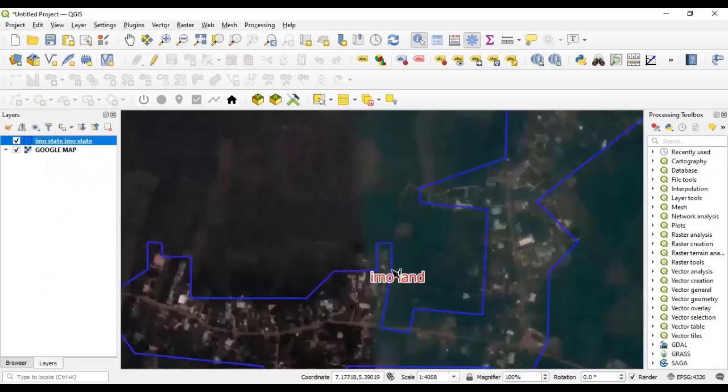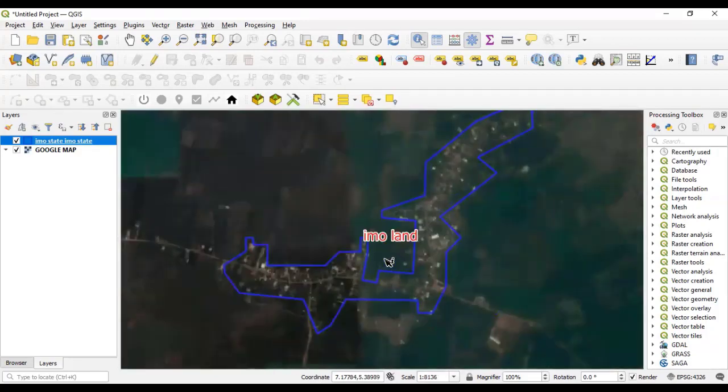So you can only use this buffering when you are using a base map, possibly your satellite image. Because if you are using a plain background, let's say a white background, an empty map, you don't actually need to use a base map and then use buffer. You see that the white outline will not show, right? So mostly you use this when you are using a base map, and you want clarity in your map.